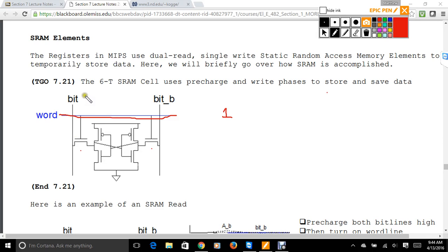So what's going to happen is, if you have a 0 here and a 1 here, right? So let's say we can actually now go through the circuit and figure this out. So now this is going to be, they won't flow through here. So what's going to happen is you have a 0 coming in here. You put a 0 here. So now it's going to go to the input of this inverter. It's going to activate this PMOS. That's going to turn up. It's going to put a 1, and you have created your channel, your inversion region in PMOS. So you have a 1. So it's going to put that here.